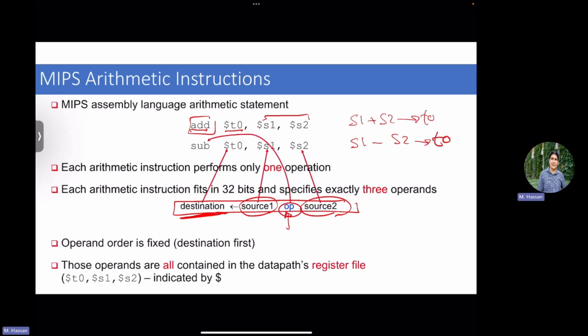And if we are talking about an R-type instruction where you are operating in registers, all of these registers are stored in a register file, and they have a certain address, right? In the MIPS, you have 32 registers, general purpose registers, which means you need 5 bits for the address. Good. Here there are some register conventions